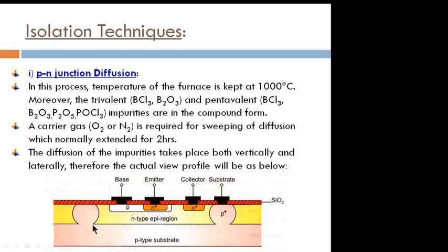Ideally it should be straight, but because of the potential well difference it gets expanded, and in addition to that the diffraction of UV light also makes the wedge not a right angle but a little bit widened. So all these issues are overruled by using a small micron wavelength, and that is done by the X-ray beam or the electron beam lithography.